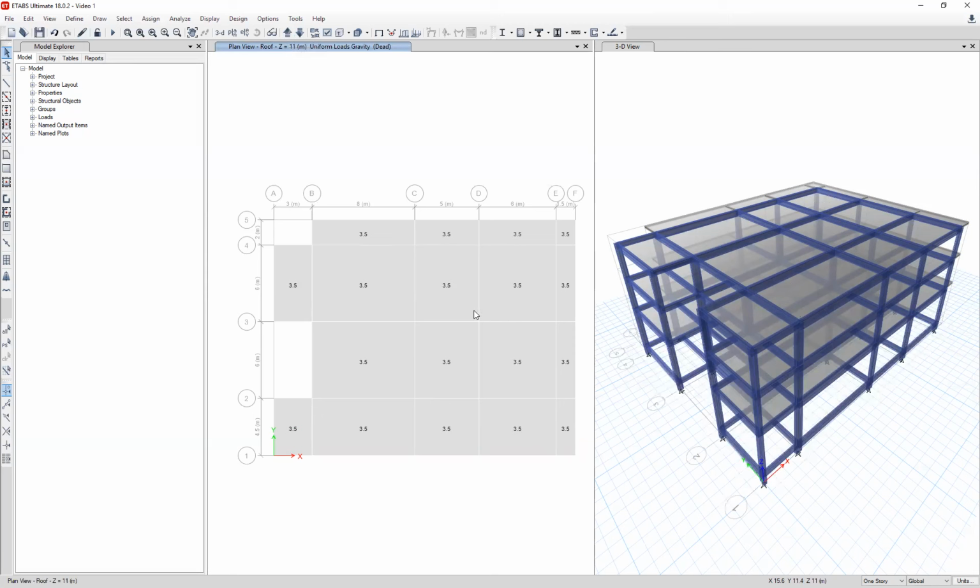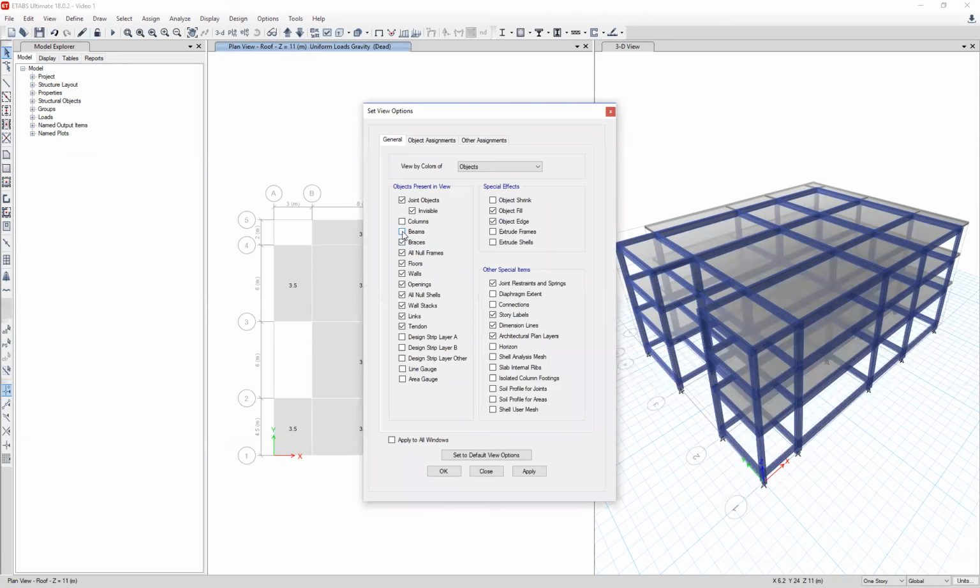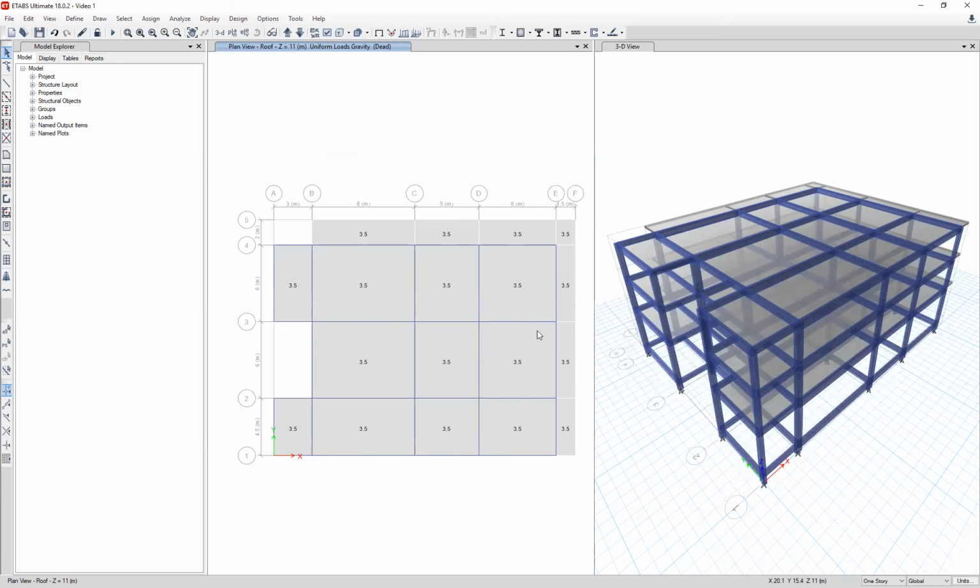This is the roof. And now, because we need to add loads on beams, we can hide the slabs, and now we can open the beams. So let's go here. Beams, we'll make them open. For the floors, we don't need to, or we keep it because we will need to add one beam. Here you can see we have a beam here, and then at these outer sides between 4 and 5 and E and F, you have a cantilever.